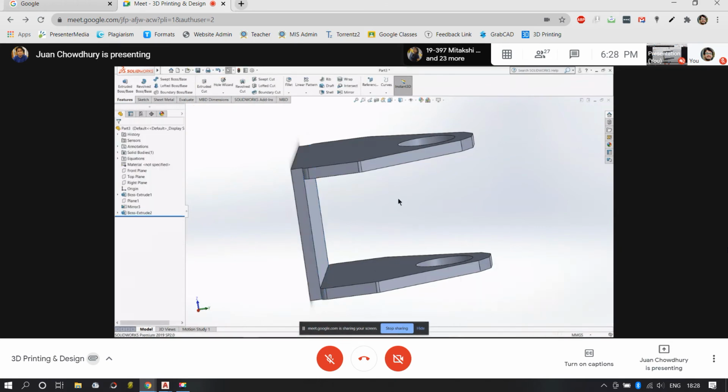Very important in context to 3D printing, because there should be a continuity of elements. If there is a break in between, the continuity gets missed and you will have some aberrations while printing which you were not predicting while modeling the part.